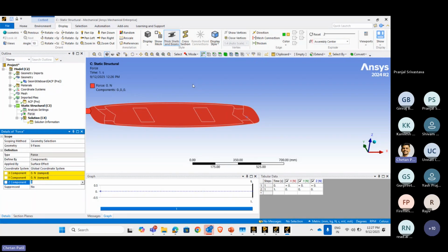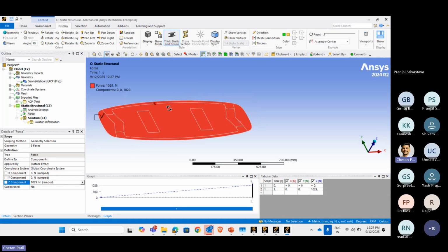should get the weight that this kite board is used with. A person hanging with it has a weight of around 115 kgs. So in terms of Newtons that I can apply, it is something like 1029 Newtons. That I'll apply on these surfaces of the geometry. Now this is the loading condition that was provided for this model.